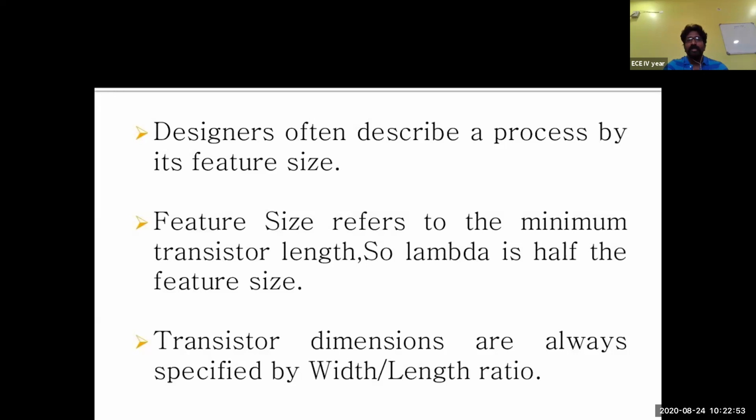Different kinds of op amps and digital circuits have been given there. You can look into how each and every transistor has to be designed, and how we should take care about the VGS value, that's the gate to source voltage. All those things are very important while designing this particular process, and also to specify the feature size, that is the width and length of the particular transistor.